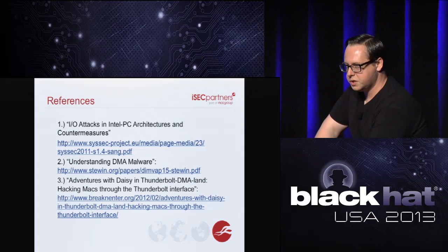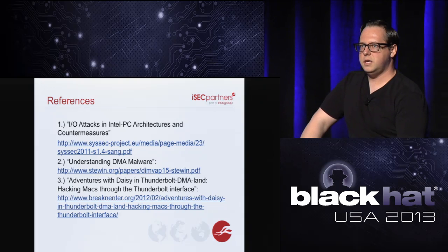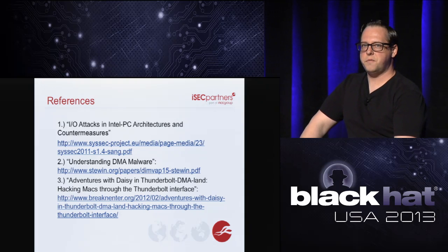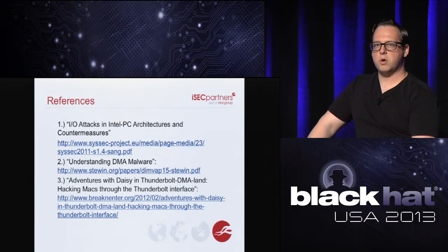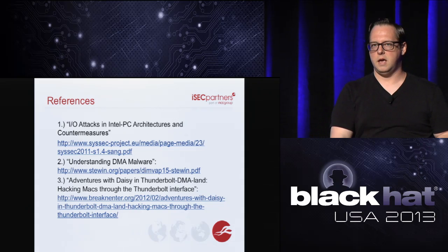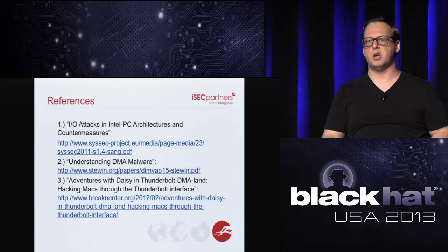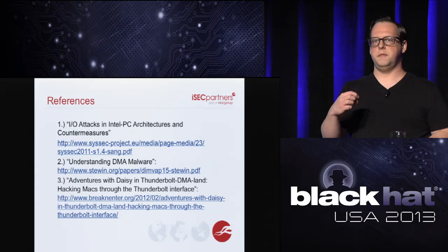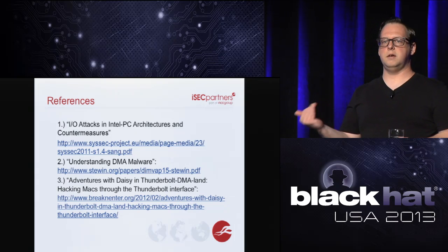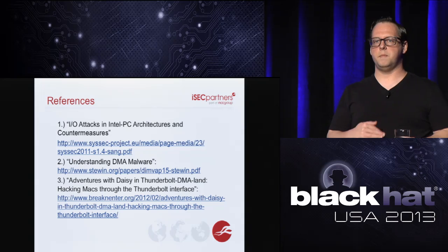I'll try to answer the question the best I can. I used the Altera Cyclone 4 GX stuff that came with Altera's Quartus 2, and the hard IP is kind of on the FPGA itself, so there wasn't actually a soft IP version that I needed to configure. What happens is the Quartus 2 software will actually connect to the FPGA via JTAG, and it'll program the hard IP for PCI Express.